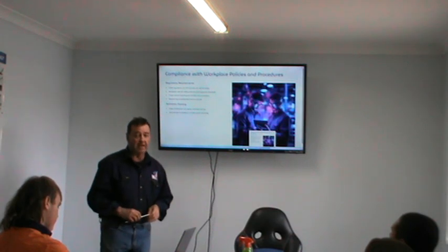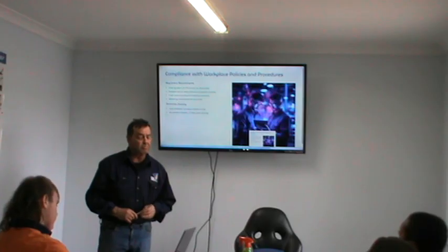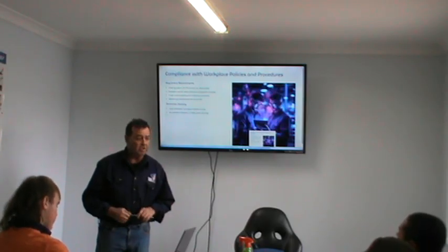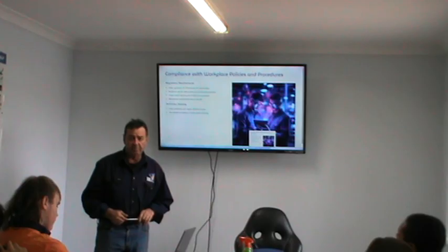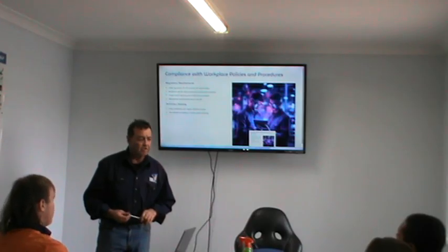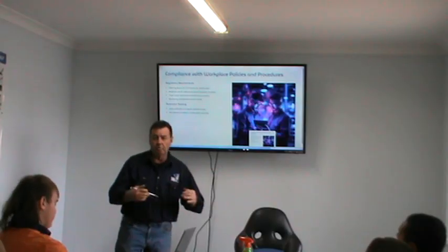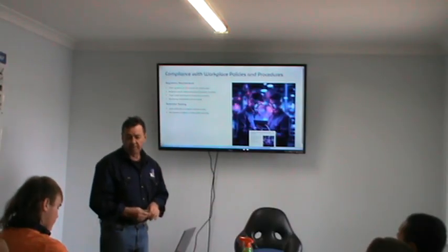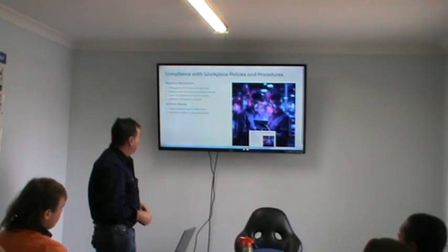We always got to maintain our records. When we're disposing of old brake fluid, it's obviously got to be taken as toxic, so it's got to be removed by a licensed person that removes that sort of stuff. So you would have to have a liquid hydrocarbon bin for all your liquids that come out from a vehicle to be stored in, to be taken away.